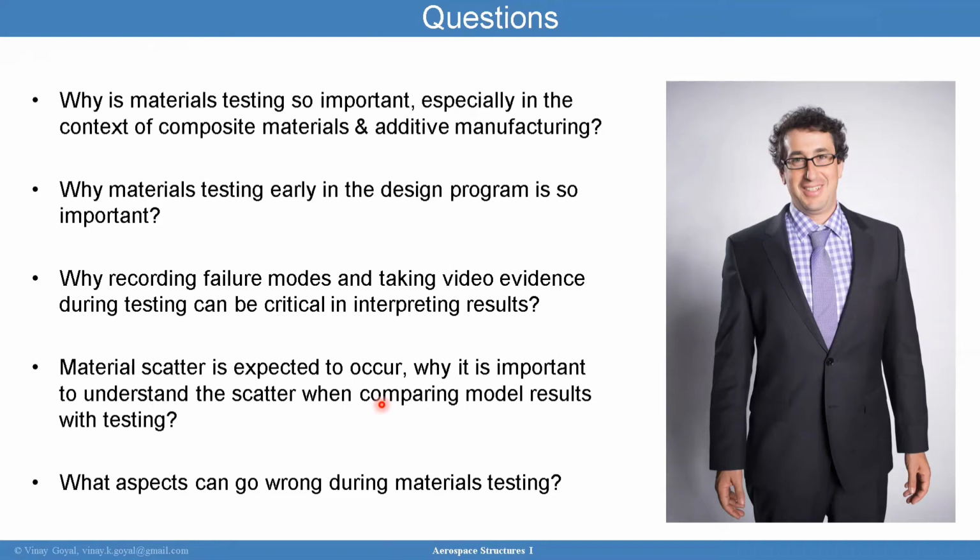And finally, you could have testing issues. For example, he has just shown us the 3-point bend test, where the rotors were applying localized failures, causing a reduction in strength. So new approaches had to be looked at, like using rubber. But again, it shows that even the testing itself can be wrong, which maybe is not the analysis. Sometimes it's the testing also. Is that well summarized?